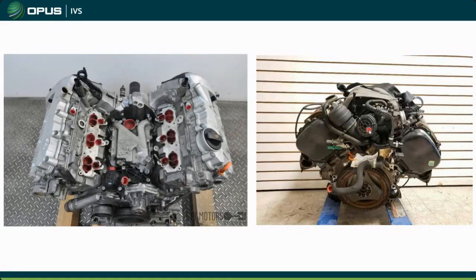Some of the common failure points obviously are these hoses. They get brittle. That corrugated plastic starts to disintegrate. Inside of here is a pressure regulating valve, which has a diaphragm. I've seen them rupture before, but for the most part, a fairly simple system.